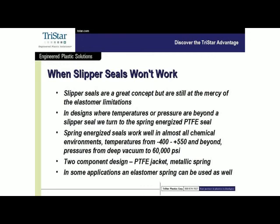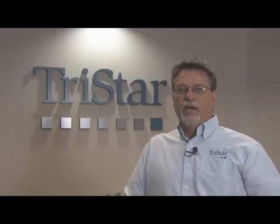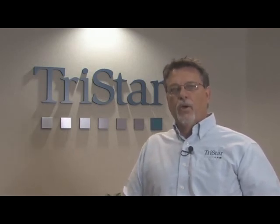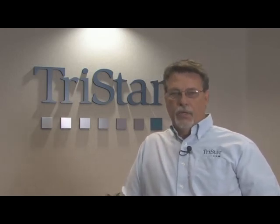In some applications, quite honestly, we'll use a spring energized seal and the spring will be an elastomer. There are some applications where that's important, like in certain compressor conditions, you can't have any dead space at the top of the piston. Then you need to have something other than a spring in there. So sometimes we'll use an elastomer or we'll combine an elastomer with a helical spring, something like that, to take up that dead space.